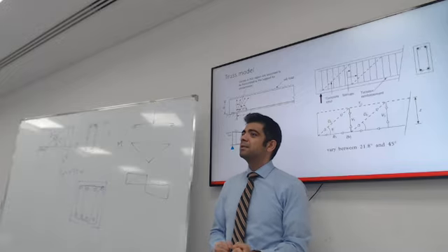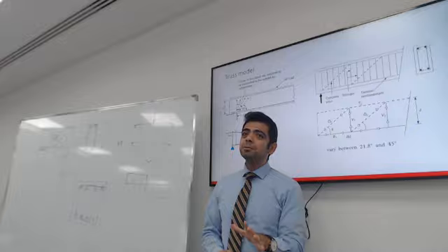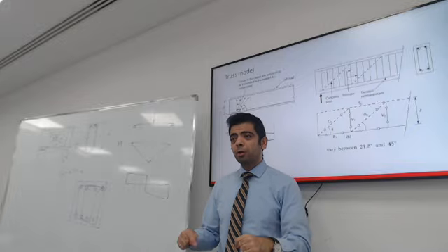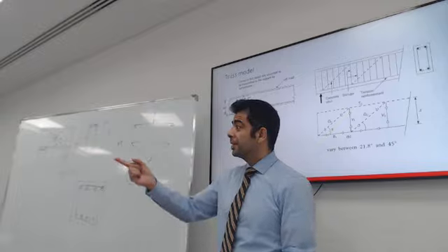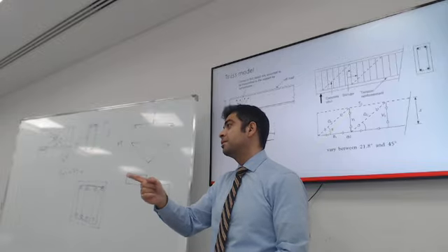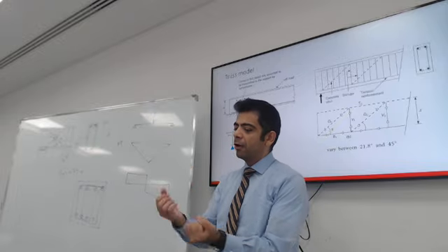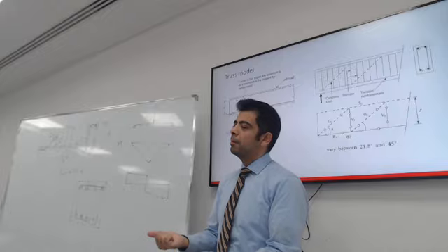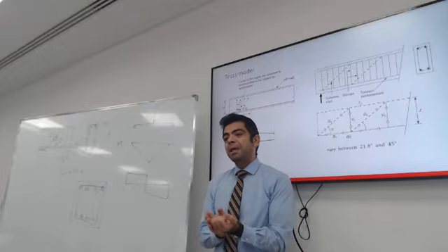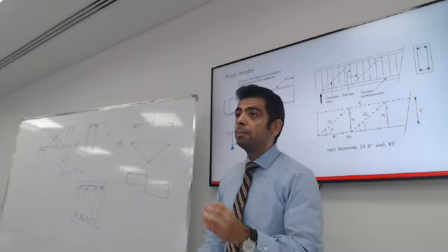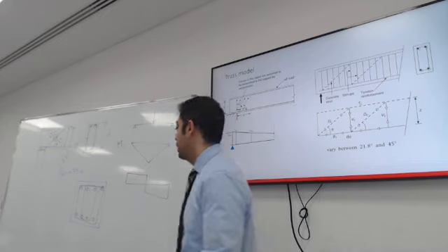Does that make sense? Does that worry any of you that shear will add more load to the bottom reinforcement? Shouldn't that be increased? Yes, definitely. So shear has an effect on the forces in the bottom bars. But the way we do this is we extend the bars beyond the point we need them.